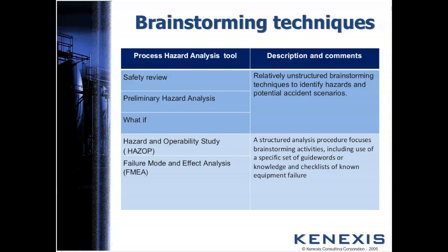Conversely, if you add the what-if portion, then the checklist portion gives you a more systematic way to explore the what-if analysis, so it's a good hybrid technique that combines the creative brainstorming features of the what-if with the documentation capabilities of the checklist, okay? And it's used during many phases of the plant life cycle.